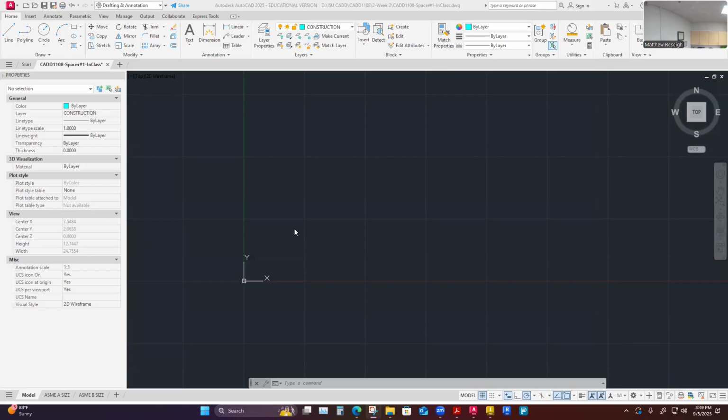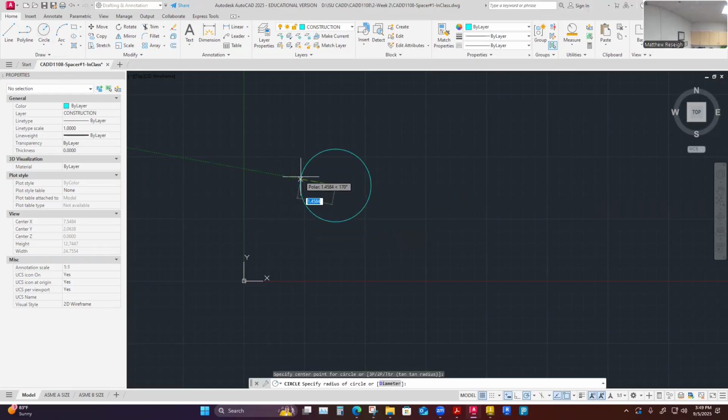I'm going to make those arcs with full circles and I'm going to trim them. This is just a way to do it. Anytime you see me draw, there are so many ways somebody sees that shape and how they want to modify their existing draw commands. The way I draw this is one way of many. So the first thing I'm going to start with is maybe a center radius circle. It's kind of helpful to start. So I'm going to pick circle, center radius. I'm going to pick this center.